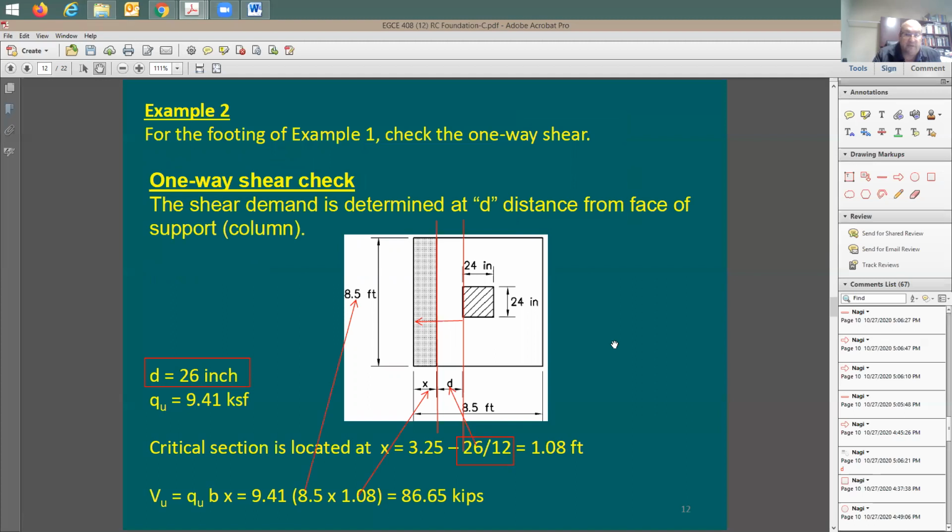So I guess you guys now understand how we handle foundation. It's going to be very similar to a beam in terms of checking of the moment and the reinforcing, and also check on the shear at one section. But this is not the only thing. We have more things to come.